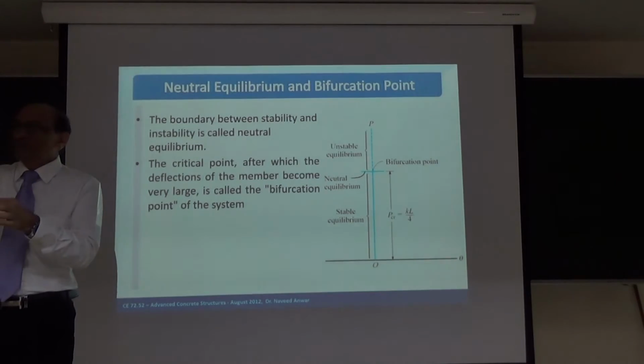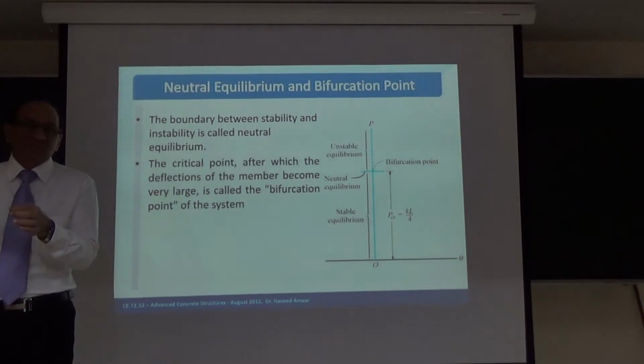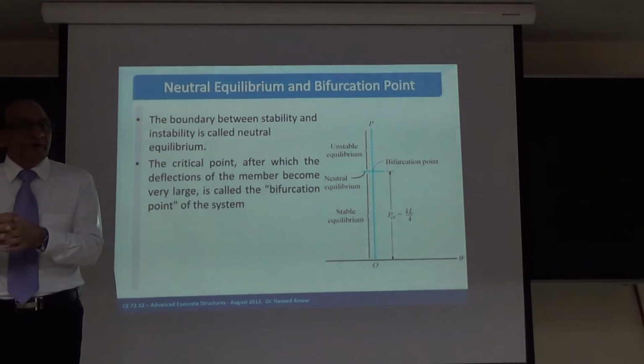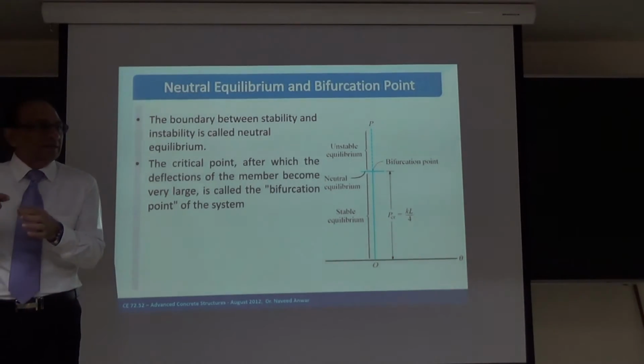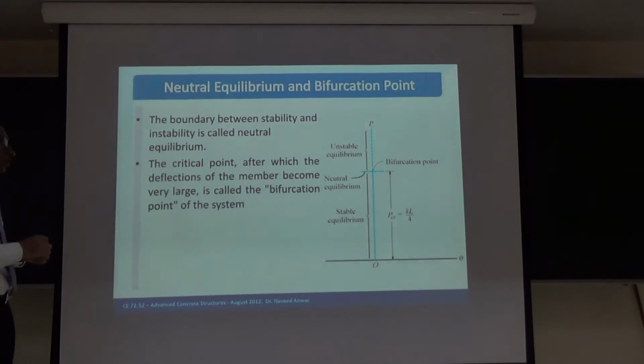So if you plot a deflection, depending upon which deflection you are plotting, you may not see the buckling. So that is an interesting part, because the buckling can happen in many directions, and it can go suddenly. So bifurcation point means that we don't know what will happen at that point. There is also a phenomenon called snap-through buckling, which, okay, I don't want to complicate too many things.